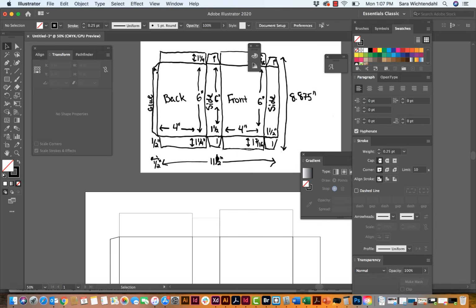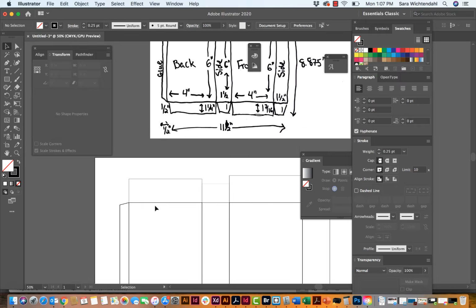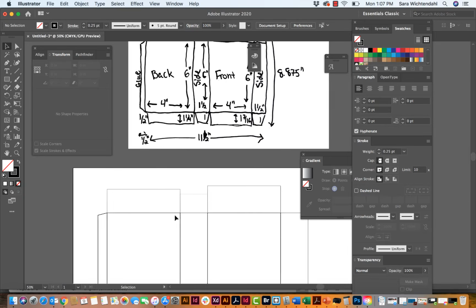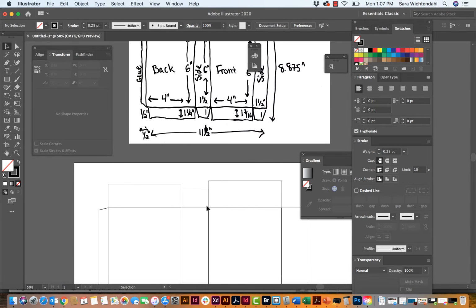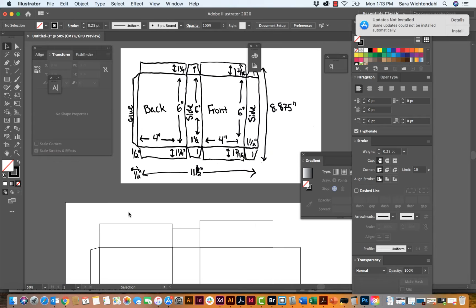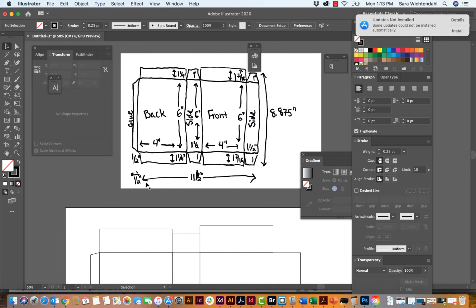But the other thing, whereas we tapered these glue tabs, we also need to taper these flaps. Because again, unless you perfectly fold, you are going to see they will start running over the edges. So we need to do a little bit of tapering with these flaps. And you'll see that if you look at professional die lines, they will have a fairly large taper to them. So now that I have these shapes along the top, I need to go ahead and taper them just slightly so that way they tuck in.